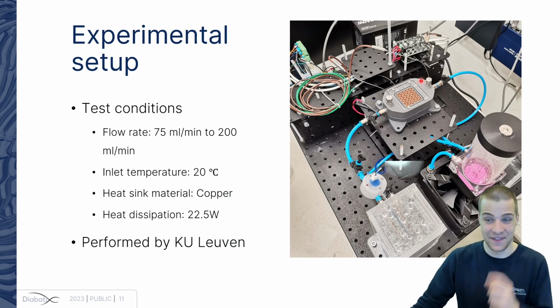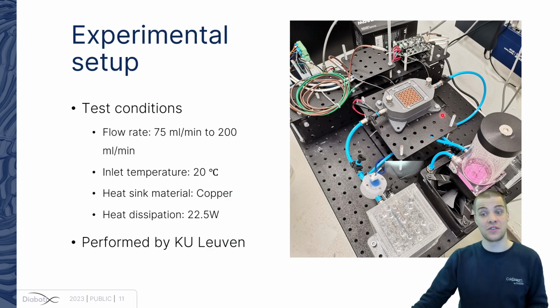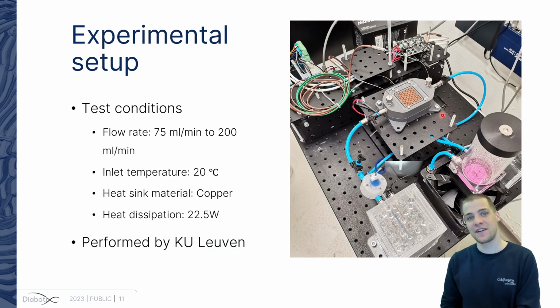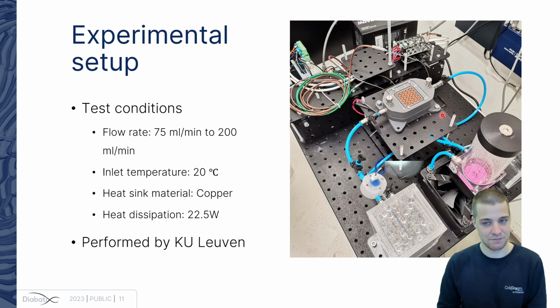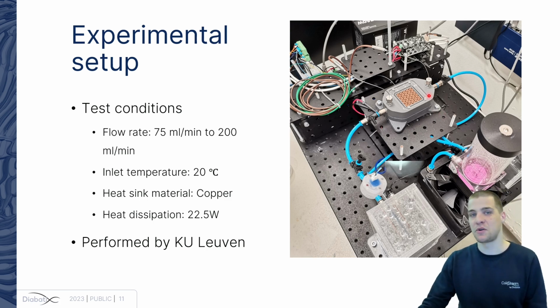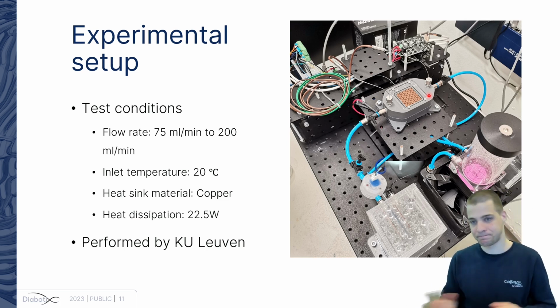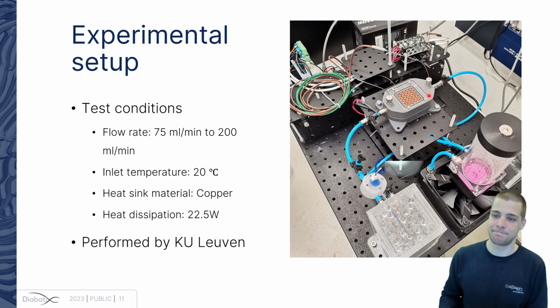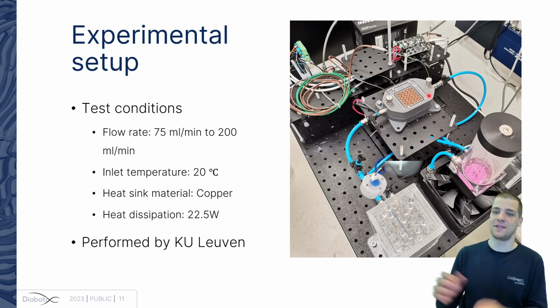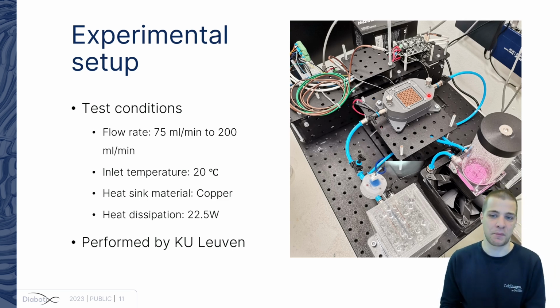Yeah, that's a very interesting question. My thoughts on gyroids. If you purely look at the heat exchange of gyroid geometries, that's very good. That's very clear from the literature already. But pressure drop wise, it has quite a big pressure drop. If we're honest, for heat exchangers to solely rely on gyroids, I think there are other solutions that are better. Basically, the penalty for pressure drop is a bit too high in my opinion.